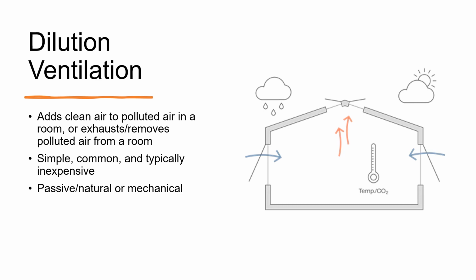So the cooler air is flowing in through the windows, and the room inside is warmer. So then that air warms up, rises up, so the contaminated air gets pushed up and out of the openings in the roof. So this is a passive way of using dilution ventilation to clear dirty air out of the room.